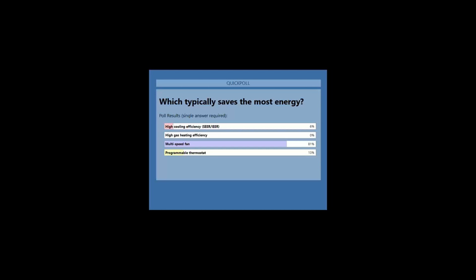Or you might have one compressor like this unit, and the unit behind me over here, one compressor that runs at 2 speeds. That's nice because then I only have one thing piped in, makes things a little bit easier in that regard, and it's a little bit less expensive. Most 2-stage residential units are like this. They'll have a 2-stage compressor. Small commercial units, typically 3, 4, 5, 6 tons, use residential compressors, so they're typically like this as well.